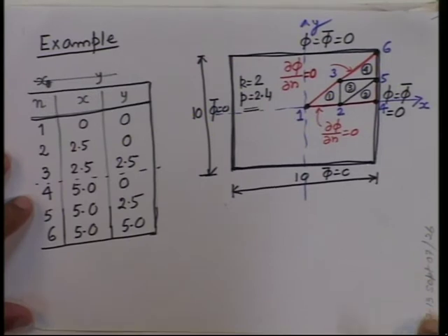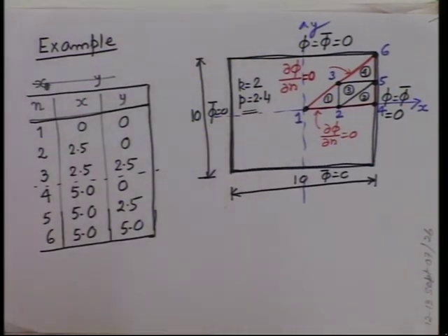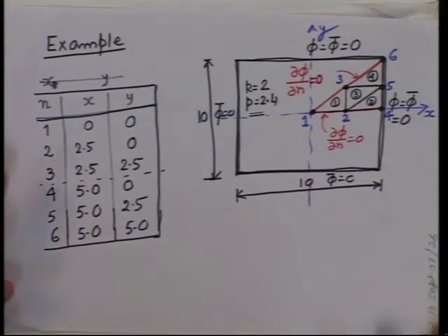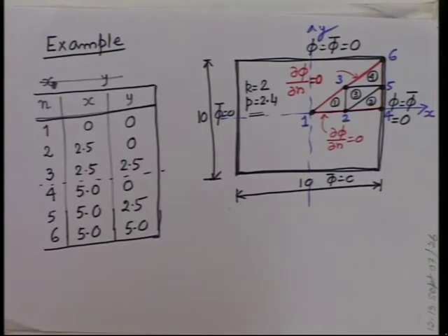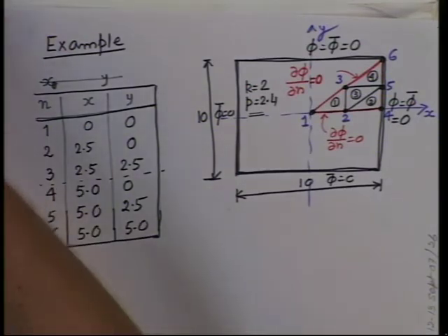This is the problem that we took, and then we discretized this small 1/8 because of symmetry, into 4 elements, and then I told you these are the coordinates of various nodes, and you have to find out the K matrix and F matrix for each of the elements.